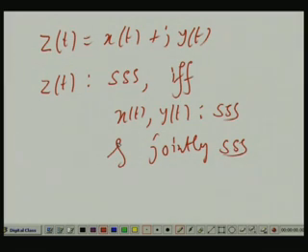This strict stationarity is more theoretical in the sense that it is an absolute notion of stationarity, and that is why you talk in terms of the absolute statistics, that is probability density. As you know, probability densities define everything. If you know all the probability densities, individual and all joint densities of the process, then the entire statistic of the process is characterized. So, when I define strict sense stationarity in terms of statistics remaining invariant on the choice of time points, then this is really an absolute notion.